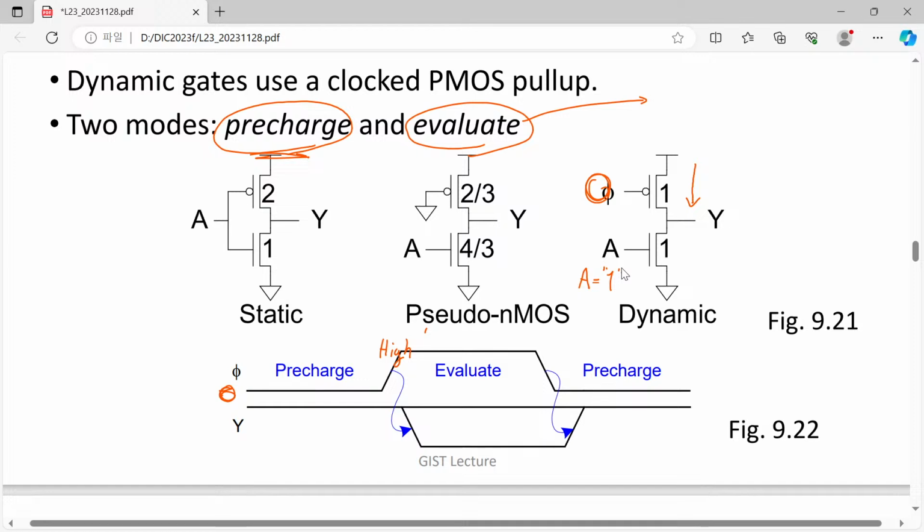In this case, the PMOSFET is turned on, and unfortunately our N MOSFET is also turned on, and both of them will try to conduct current. So from VDD to ground, there will be another current conduction path. That is not desirable, because the main reason why we introduced this clocked signal for our PMOSFET was to avoid this current.